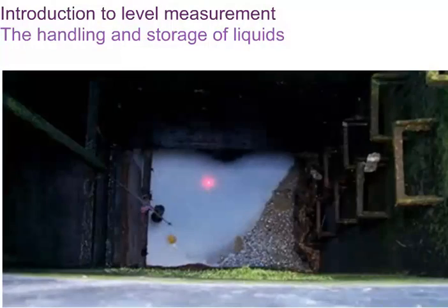Level measuring instruments that work on liquids may not be suitable for use on granular solid materials. For example, differential pressure transmitters only work with liquids, while a plumb bob instrument only works on granular solid materials.